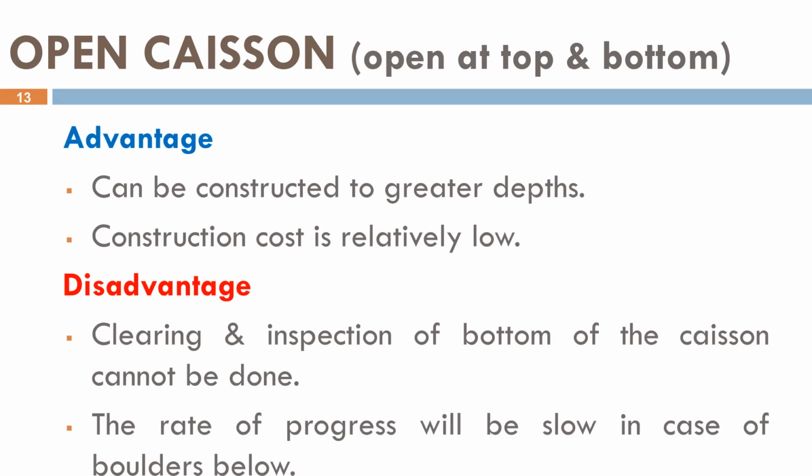The advantages of open caisson are: it can be constructed to much greater depths. It is relatively economical for bridge foundations. Its disadvantages include: the bottom cannot be inspected directly after sinking. Progress becomes slow if boulders or hard rock layers are encountered.